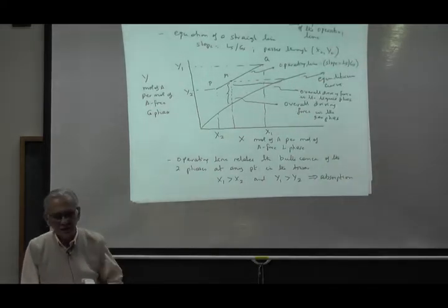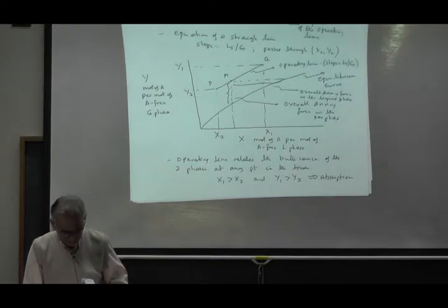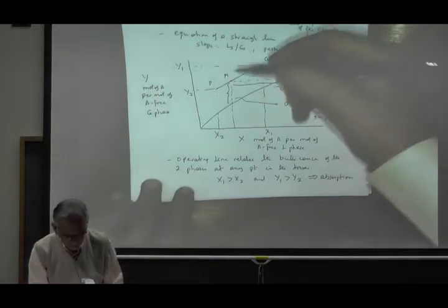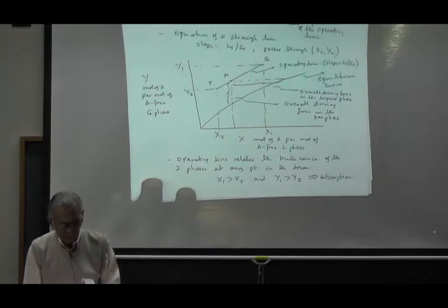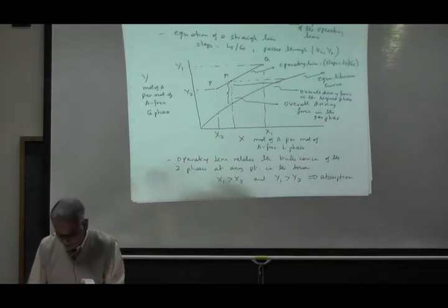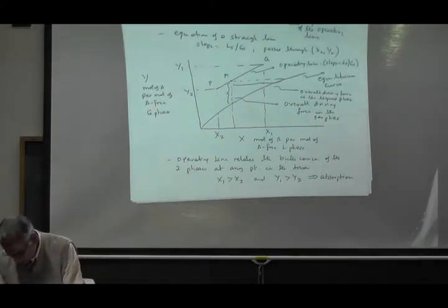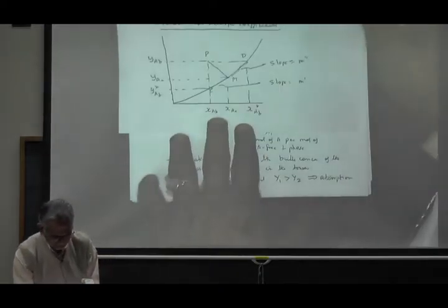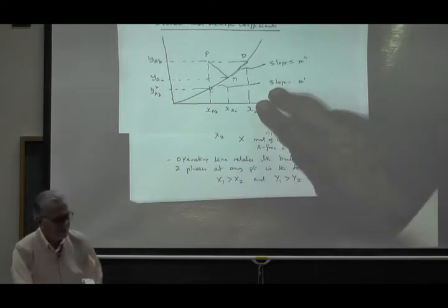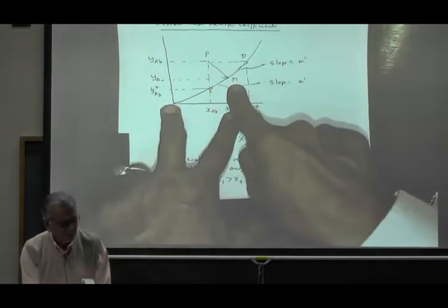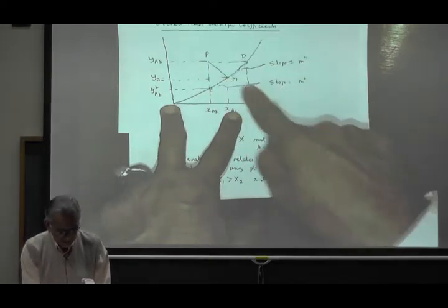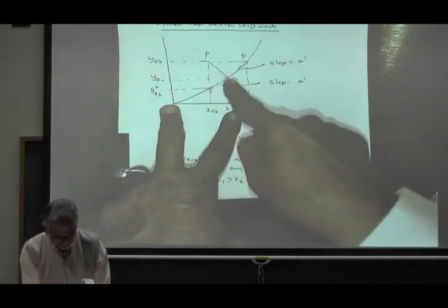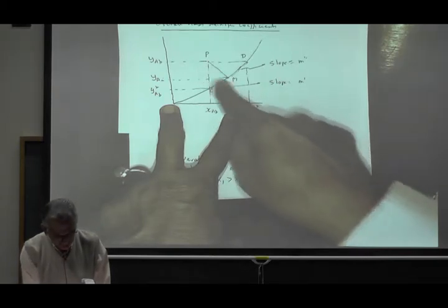What are the interfacial concentrations? For point M, what is the interfacial concentration? How do you get the interfacial concentration? Where is that graph? I don't know whether I have it today or not. Don't forget that curve. This one. This was any point in the tower. What is the slope of this line? What is the slope of PM?